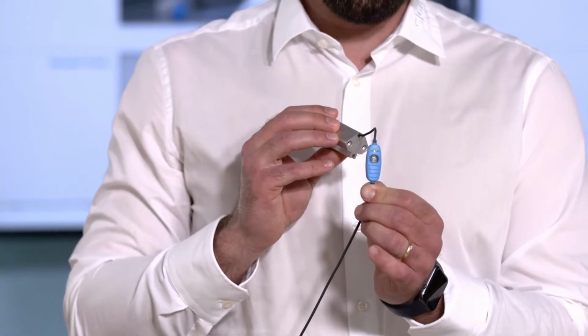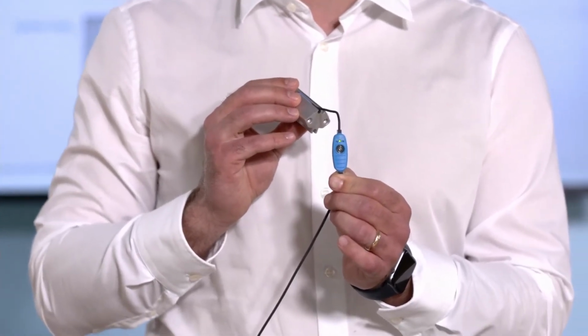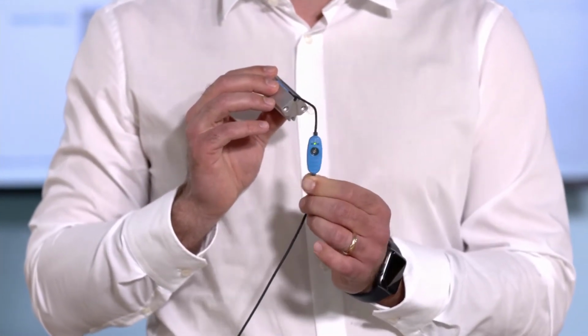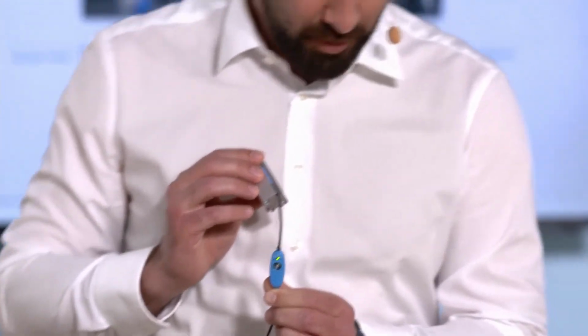The separate teach unit is for the configuration of the switching points, respectively the measuring range. Main applications are the monitoring of gripping process and the end position detection on small cylinders. MPS-G offers in general three innovative functionalities. The dynamic teach, that means that the sensor is able to set the switching points automatically due to the application.